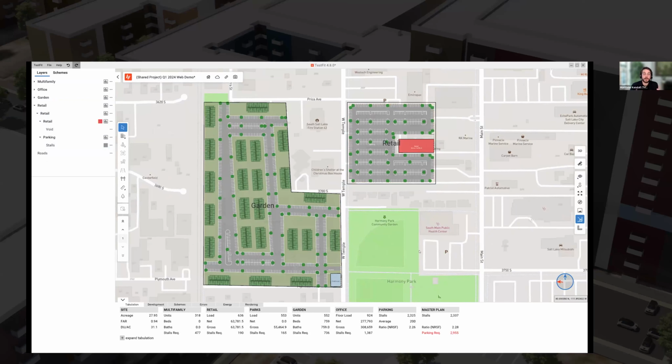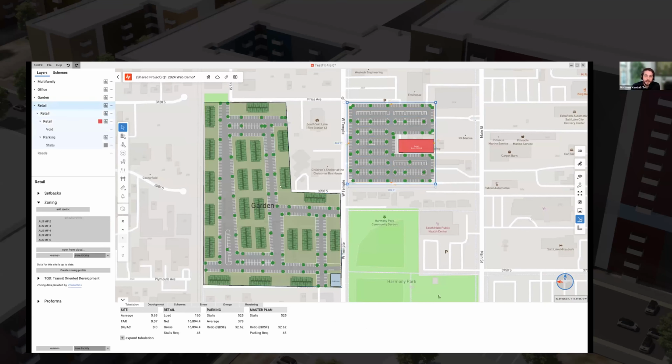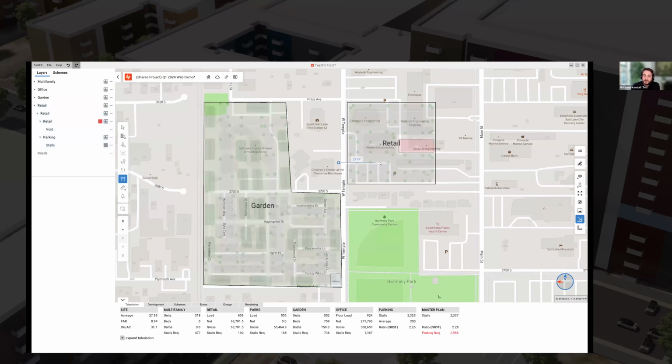Another big thing that we added is, of course, this new UI that we're using. This is going to be a big difference from what we've had previously. We did have a plus button before, which had all of the elements that you would use to add additional information to that site. We've taken that out, and we've created all of these over here on this left side. This is where we'll be able to define a site, draw it, define by parcels, draw a site, or use the metes and bounds that you have, as well as some other things we'll see inside of here. So let's say I select the site, I can add additional regions from here, add spaces, add parking, draw the roads that we use from the initial piece, or even draw easements, just to show what that easement is.